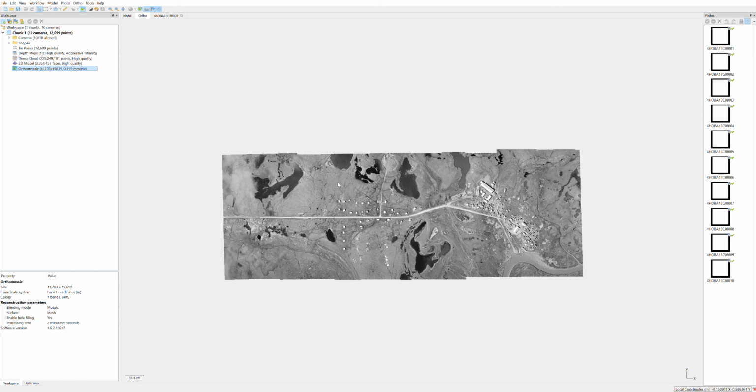To actually get this georeferenced, all you have to do in ArcGIS is just bring it in and it'll bring it in without a coordinate system, so you could either georeference it first or define the projection first. When you georeference, essentially just find something that looks similar to today, like maybe just this tank farm location, and then georeference it to that spot, and then pick something else like a lake over here, and georeference it just roughly at first, and then fine tune it later and delete your initial rough points, and that'll give you a really good georeference product.